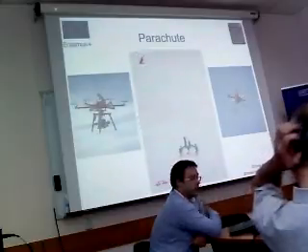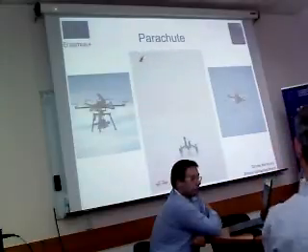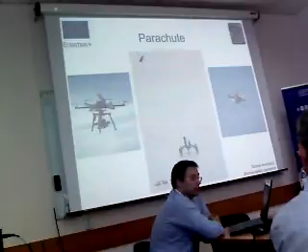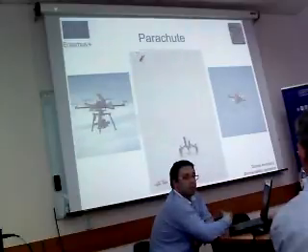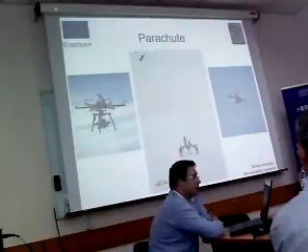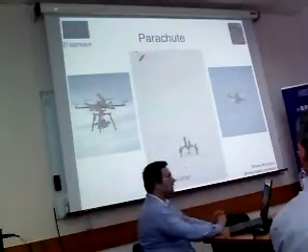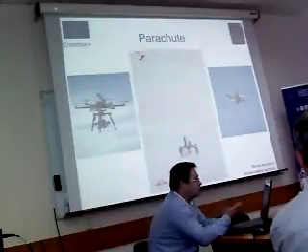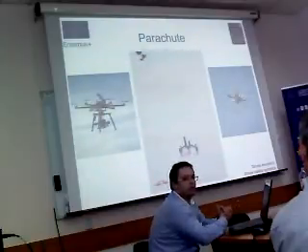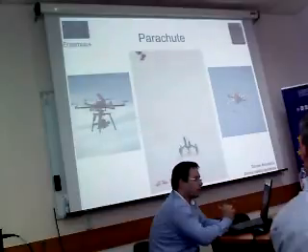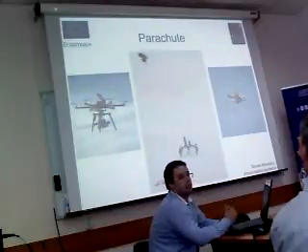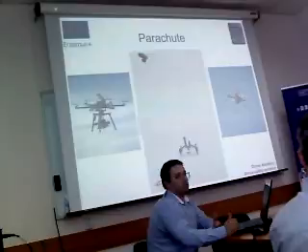What is important, rearming the launch mechanism is possible without any special tools, and it takes only a few minutes to repack it and prepare for the next launch. The producer says that it can be installed on almost any aircraft from 1 to 23 kilograms. Multiple parachute sizes are available, and up to 3 units can be installed on one aircraft.